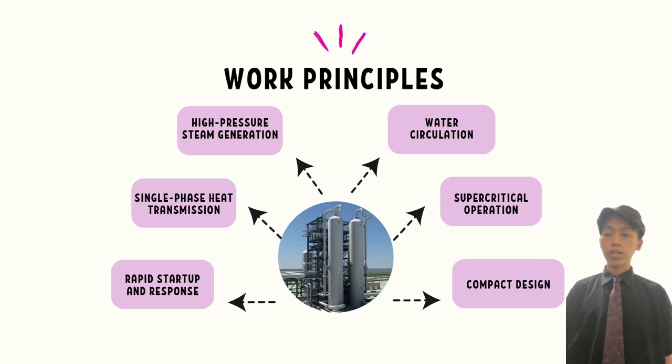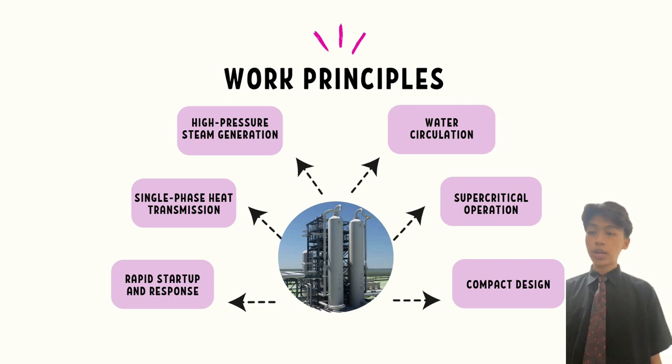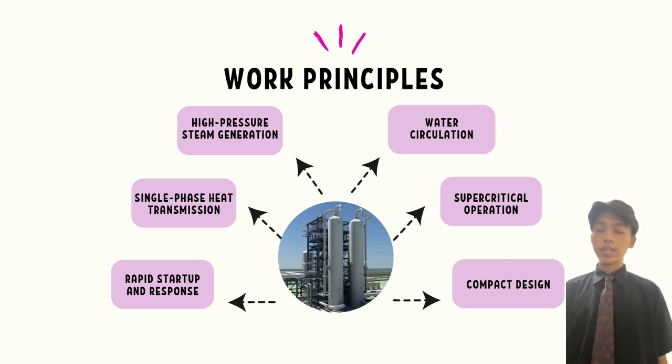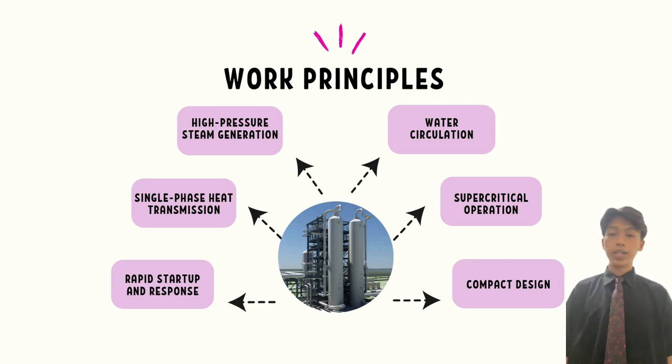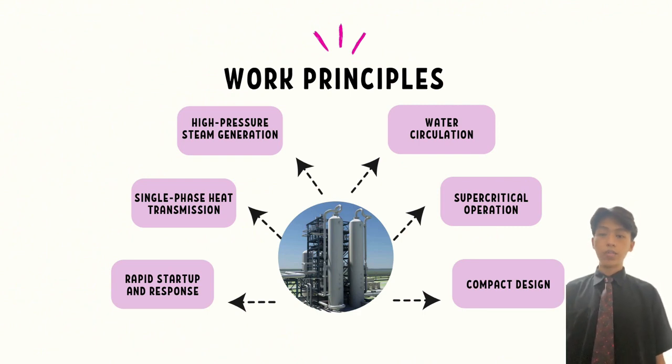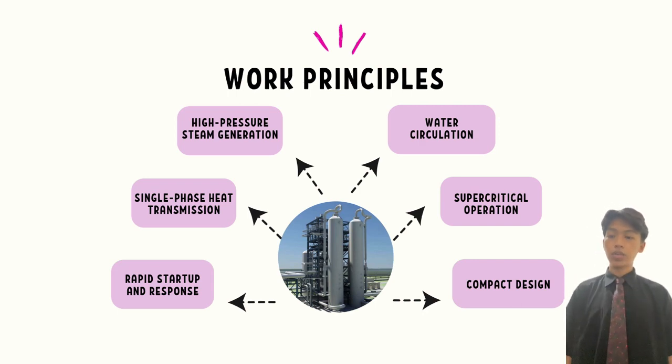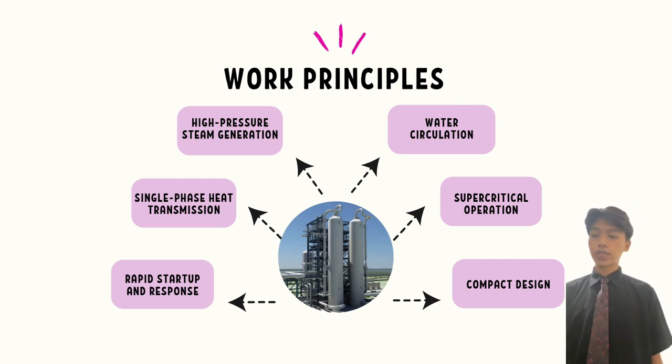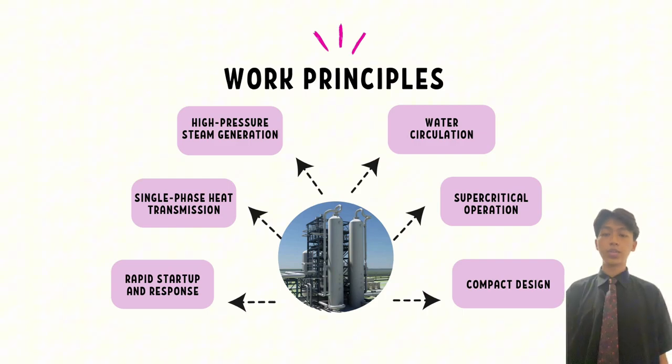Fifth, rapid startup and response. The Benson boiler responds fast to fluctuation in steam demand. Lastly, compact design. Compared to traditional boiler, the Benson boiler typically has a more compact design due to its single phase heat transfer mechanism and simplified construction.